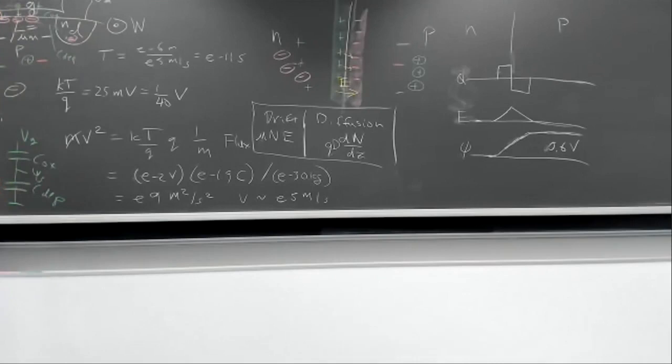Eventually you would get them, right? Just because they get thermally excited, or if you shine light on it, eventually you would get some electrons, but there's no electrons here, right? So the way you get the electrons quickly is from the source. Yes, so you need that. If you're going to make a MOS capacitor, you need that source there. Otherwise, it won't work very well, or it'll be very, very slow.